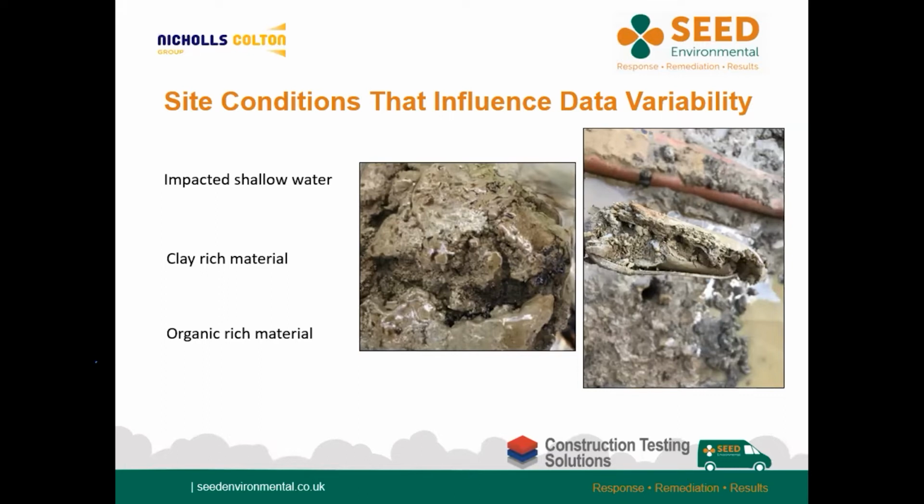It is best to try and apply a justification to what the PID results are saying and what you have seen on site, as this will allow you to present the most suitable soil samples to the laboratory for analysis. As mentioned earlier, an elevated VOC concentration may be the result of a smear on the external soil surface. So when the laboratory results return a lower than expected concentration, it can be difficult to explain the discrepancy if accurate notes detailing your observations have not been collected on site.